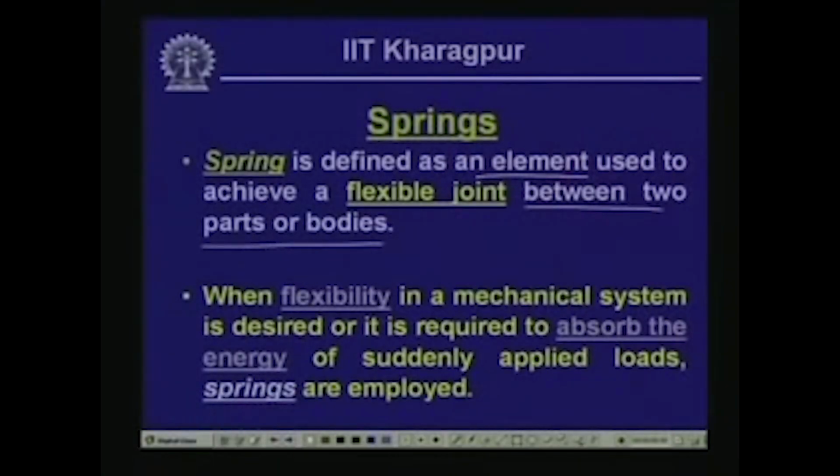Now, a spring is an element which, when loaded, undergoes movement, either elongation or shortening, and once we remove the load, the element comes back to its original position. The level of working stresses in the spring material is rather high in comparison to other structural materials. So, when flexibility in a mechanical system is desired, because this is what is needed, we introduce this element which we call